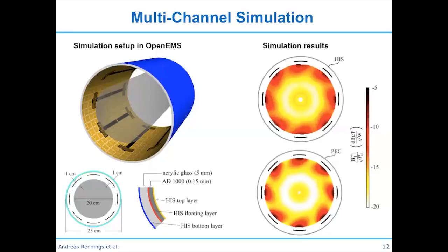You may ask, why do you have this hole in the center? It's an issue, let's say, in OpenEMS. The field in the center is not plotted in cylindrical coordinates due to the fact that at the center, along the z-axis, there is no alpha component defined.